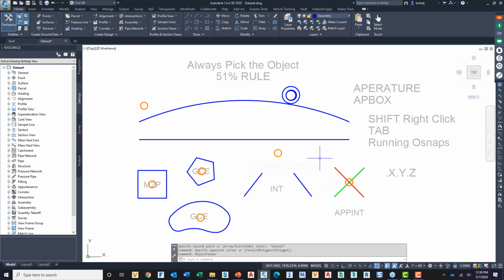Okay. Now, in some cases, if we're going to grab an object snap, maybe we want to grab an object and use its coordinates to help derive that. That's what we use what's called point filters, .x, .y, .z, or easting, northing, and elevation. Let's say, for example, I'd like to copy the circle that's down here. We'll go to a point that's consistent with the northing and easting of this corner and the elevation of this red line. All right, we can do that all with object snaps.